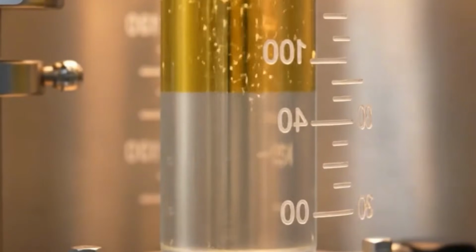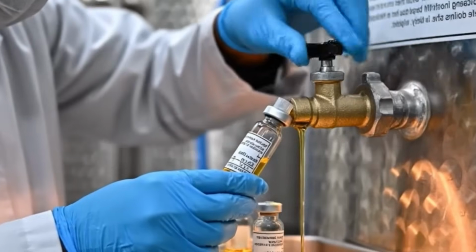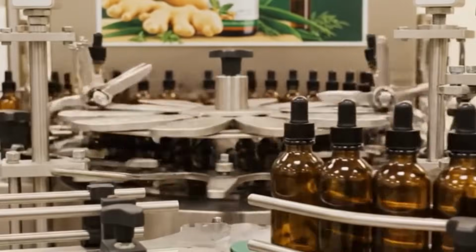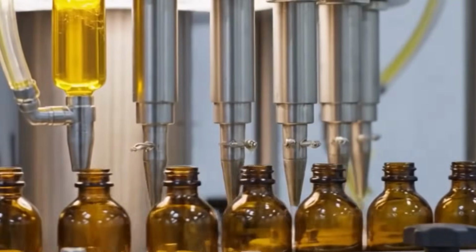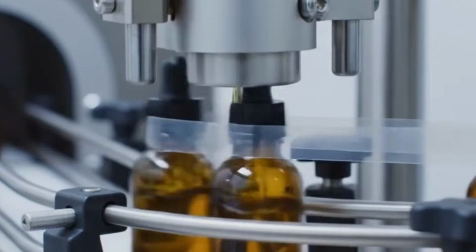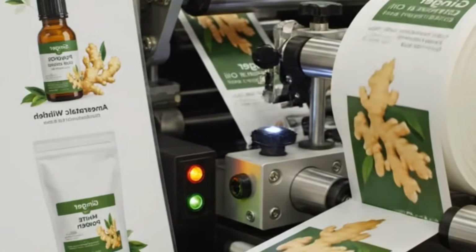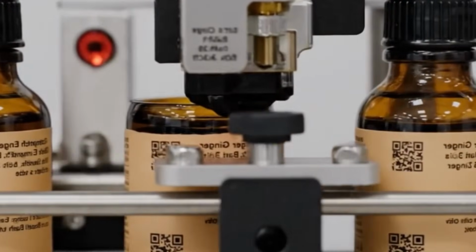plus or minus 0.1 Brix. After blending, the mixture is deaerated in a vacuum vessel. Liquid enters a chamber under reduced pressure, causing entrained oxygen and other gases to escape. The deaerated product is immediately cooled through a glycol-based plate chiller to a temperature just above 0 degrees Celsius, maximizing carbon dioxide solubility in the next step.